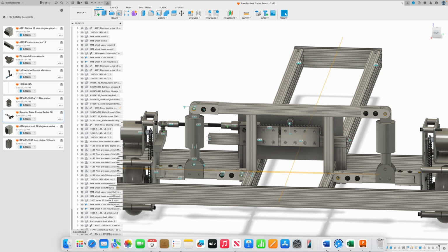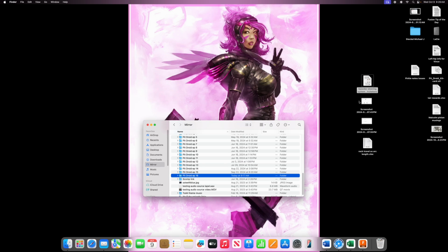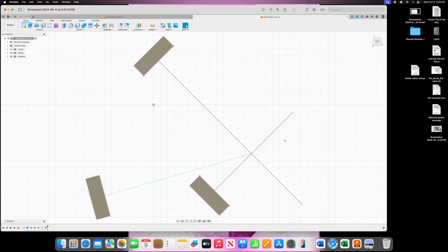Okay, so let's go back out here and talk. So this is just a simplified version. Here's our front wheel and here's our two back wheels. Again, we want to adhere to Ackermann geometry. So in a turn, if the front wheel is turned to the right, we're making a right turn. Both back wheels turn and the axles meet up at this common center point.